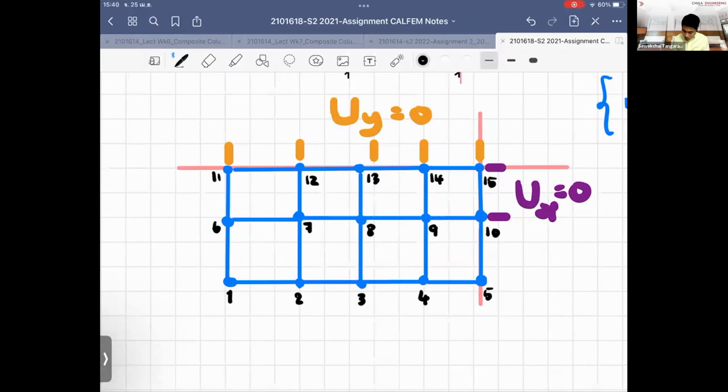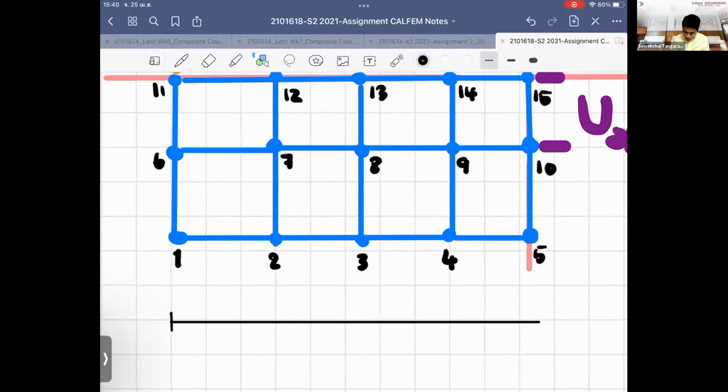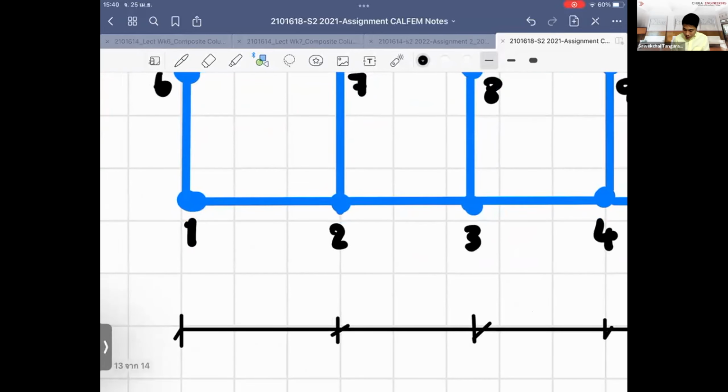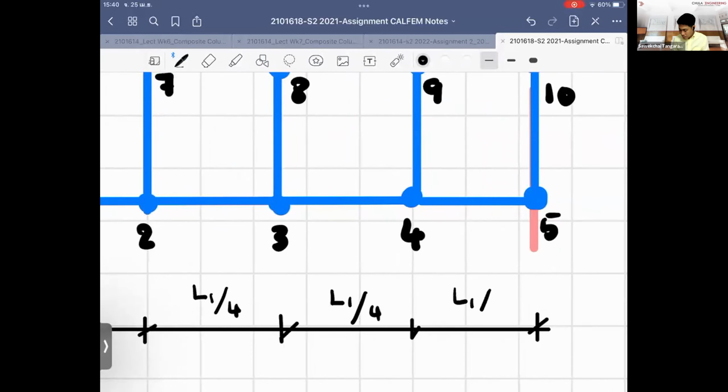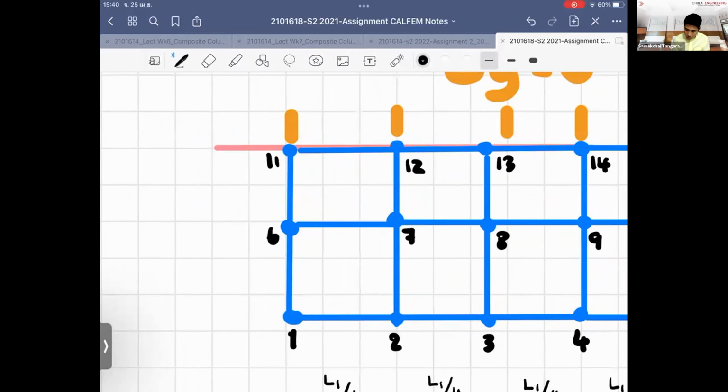And I might say that I want to divide the spacings of the element to be equal, right? Assume that this is to be equal. And if we want 4 elements along the length, the distance of this, you just take it to be equal, divided by 4. And this one as well. I just want 2 elements and I want to have it as a uniform mesh.